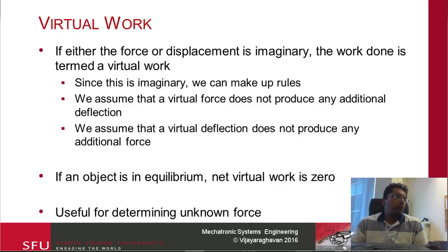The concept of virtual work is similar to the actual work itself. The only difference is that either the force or the displacement that we use is imaginary. Because it's imaginary, we can come up with any rules that benefit us. If we use a virtual force, we assume it doesn't produce any additional deflection.